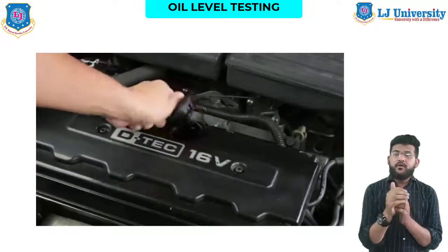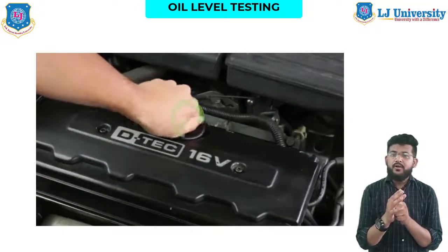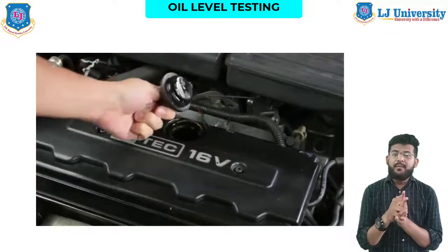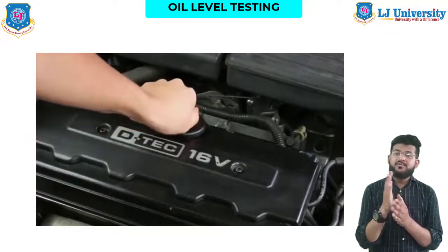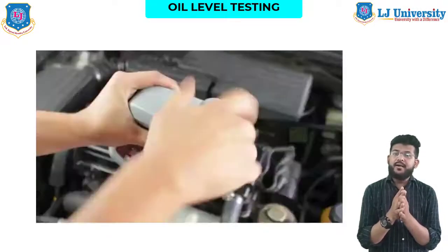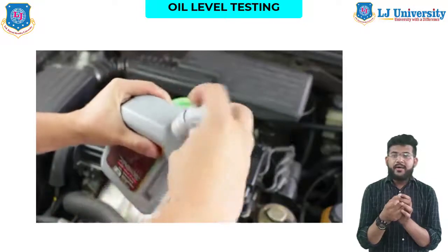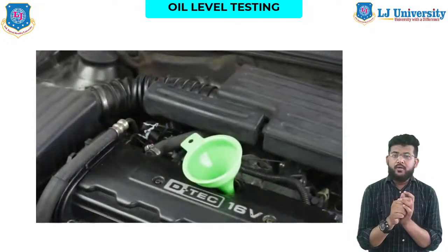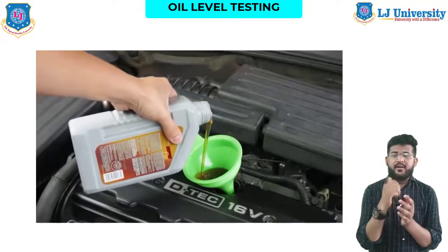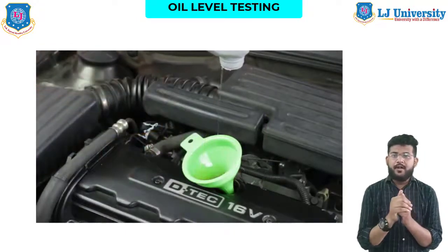Now look for the screw-off cap on the top of the largest part of the engine. It could be blank or it could be labeled oil cap, something similar to this. It might even indicate which grade of oil you should install in your car. Now only unscrew the cap and add the oil if it is needed. So just top the level up.